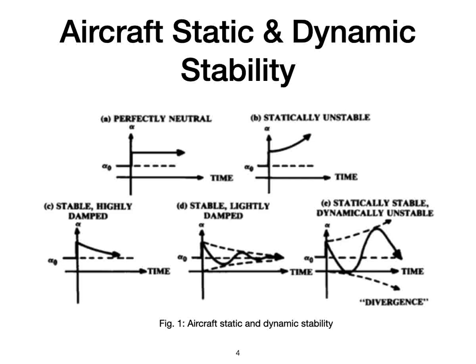In fact, pilots are generally unaware of the existence of the spiral divergence mode because the minor corrections required are no greater than roll corrections required for gusts. Dynamic stability analysis is complex and requires computer programs for any degree of accuracy.